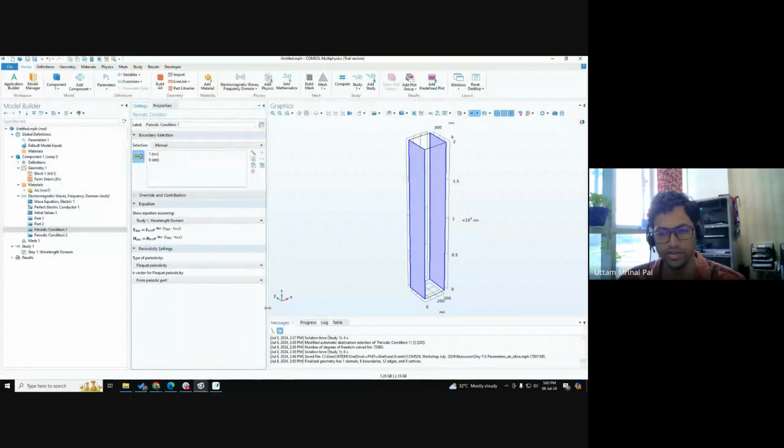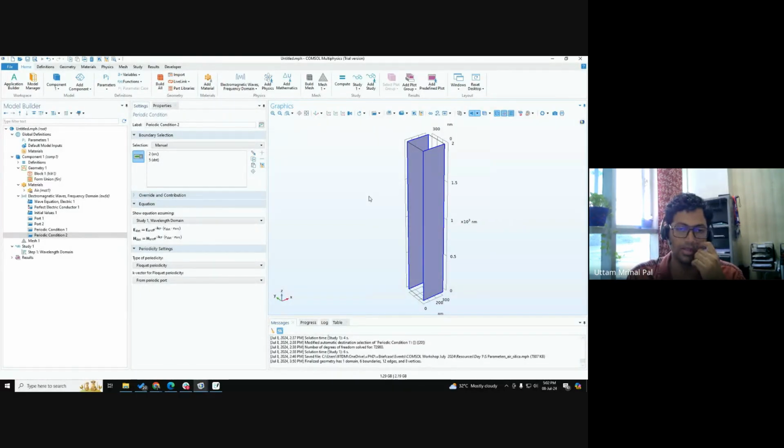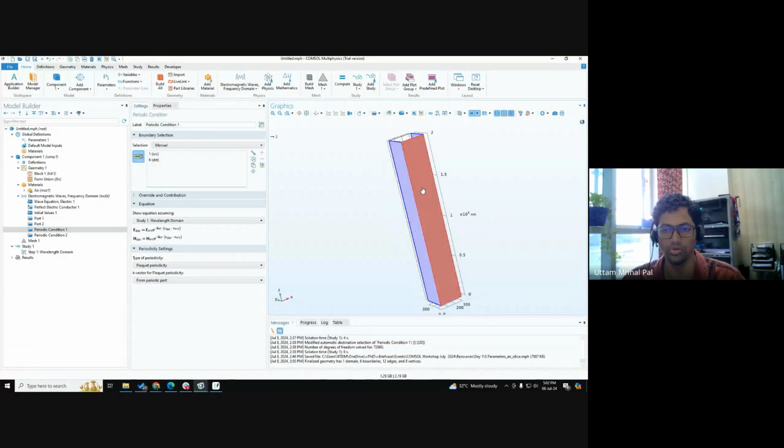Basically, if you are working with periodic conditions, you don't need to worry about the polarization. The reason we discussed PEC and PMC was for something else. This was the symmetry boundary condition. If you want to divide the geometry into a quarter part, you launch the TE or TM mode from the top and apply this periodic condition in diagonally opposite directions.